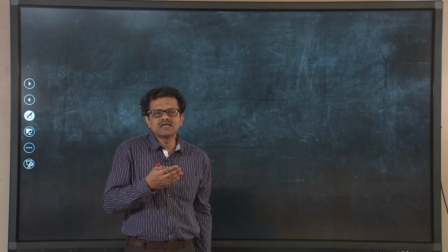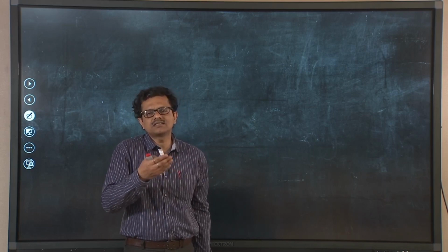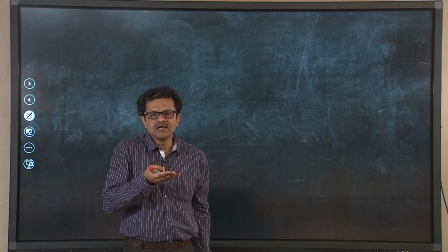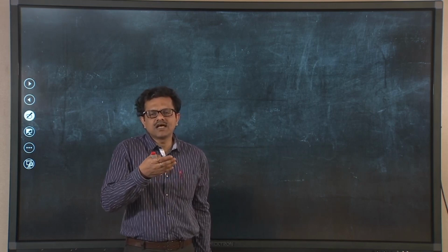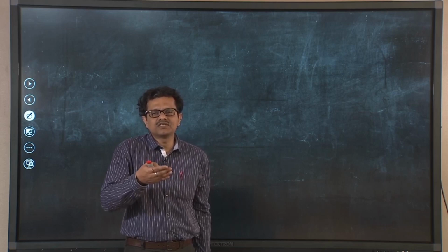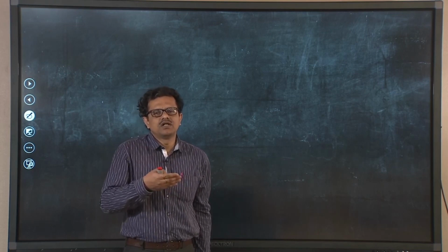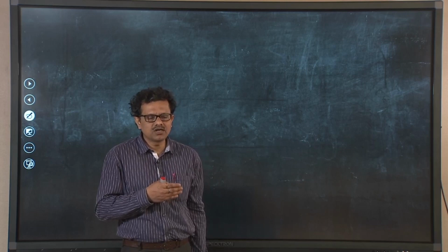But as we have discussed, if we consider single stage compression, certainly we can build that pressure, but at the exit of the compressor the temperature rise will be so high that the rise in temperature which is associated with the rise in pressure will lead to the damage of several mechanical components of the compressor. Not only that,